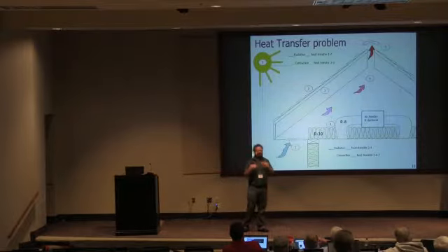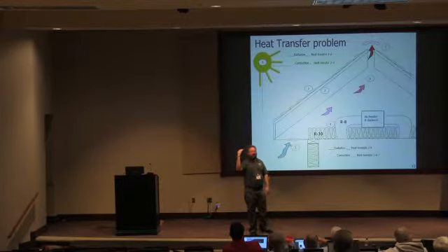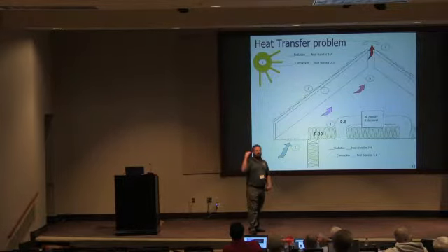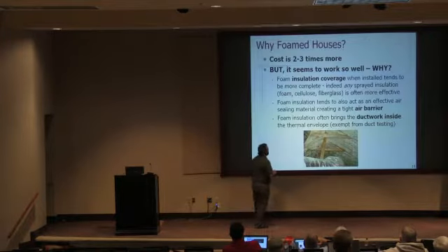And it has all these other negative effects. Plus, you're using energy at peak, right? You're running that fan when it's hot. And when it's hot, that is when the utility has the maximum demand for energy, because everybody's trying to cool their homes. So power attic ventilators is a bad idea.